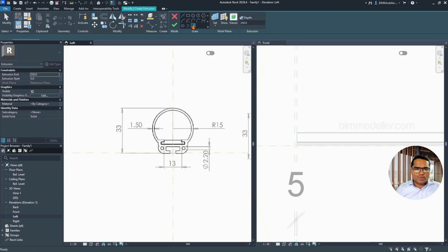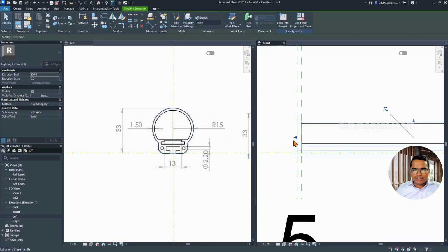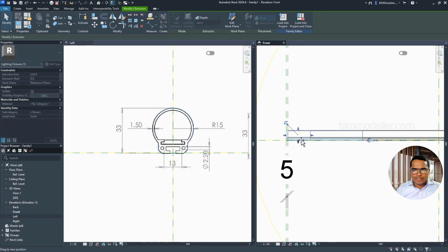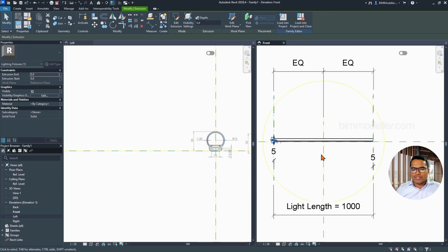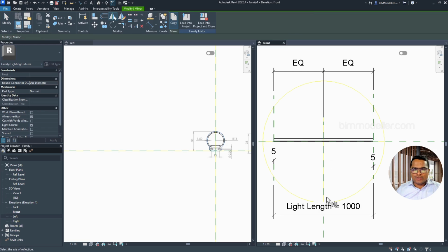Now we will be able to use the pick line since we have the outer line already. And use finish. Now if you see that it's extending further, we don't need it. We can lock it in the proper place. Make sure that it's locked on both sides. And we can do the mirror using the pick line. It goes to the other side as well.